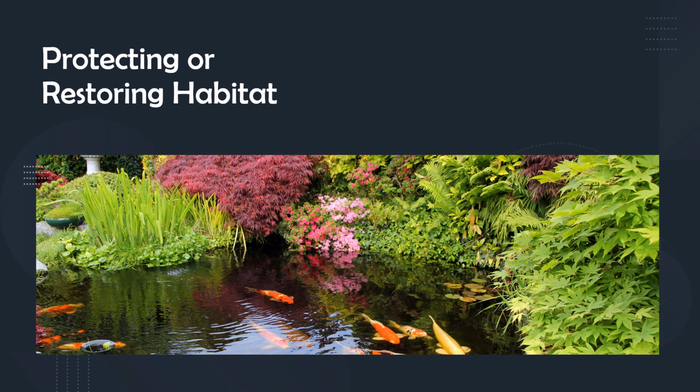You can get 1 to 2 credits for protecting or restoring habitat. The first step is to revegetate all disturbed or compacted soils in the development footprint. The requirements are to preserve and protect 40% of the greenfield area on the site, if such areas exist, from all development and construction activity. And you'll want to restore a portion of the site, including the building footprint, identified as previously disturbed, if such areas exist. This includes restoring disturbed areas in areas that will later serve as the final habitat area, and planting vegetation that is native and adapted.